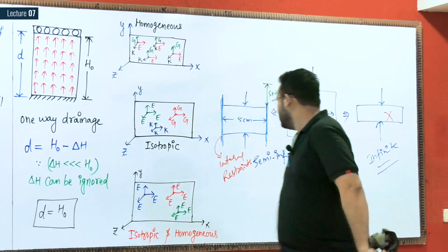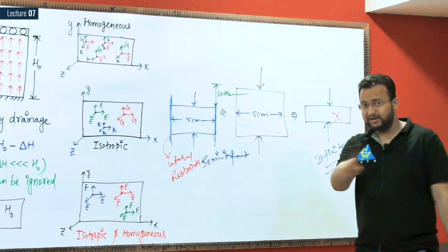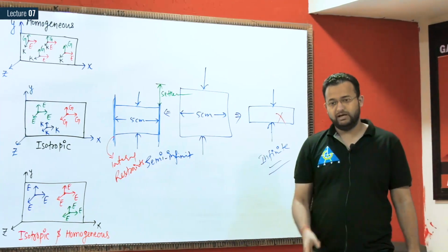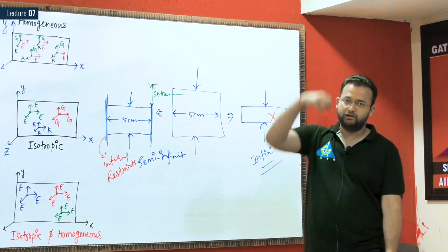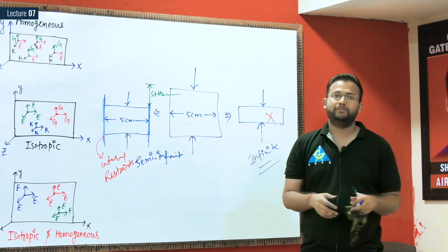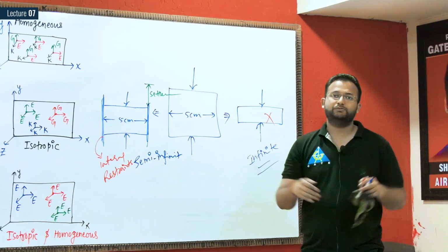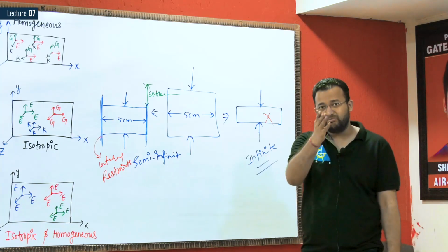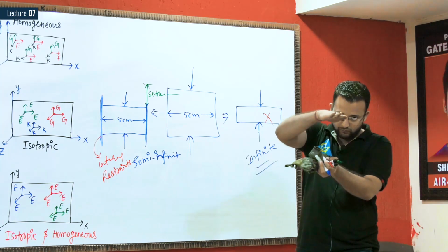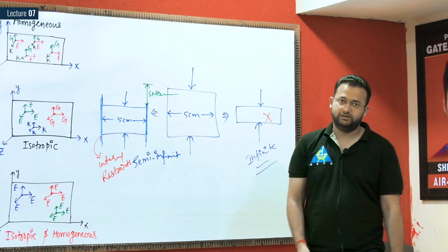So that's why we have used a ring as a specimen which is made of steel, hard, stiff. You apply the force, steel will not expand, soil will not expand, only soil will get reduced because there are a number of voids in the soil, so soil volume will reduce in the vertical direction.